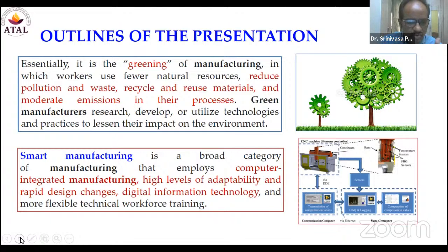If the material removal process is handled with the help of programming control, that comes under CNC machining. If the output process variables are taken into consideration to regulate the process, to safeguard the machinery and the equipment, to yield better results and give quality products, then it must be something beyond CNC operation. It comes under real-time process monitoring.